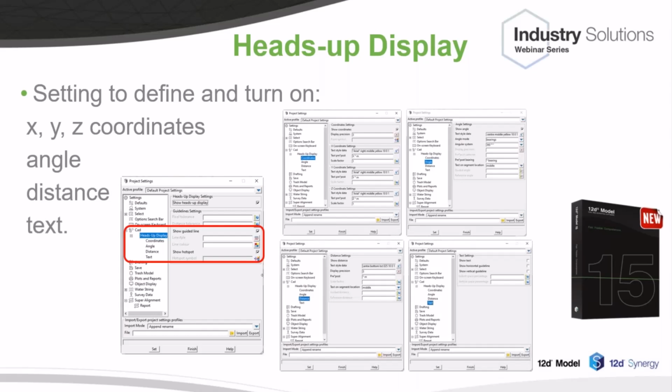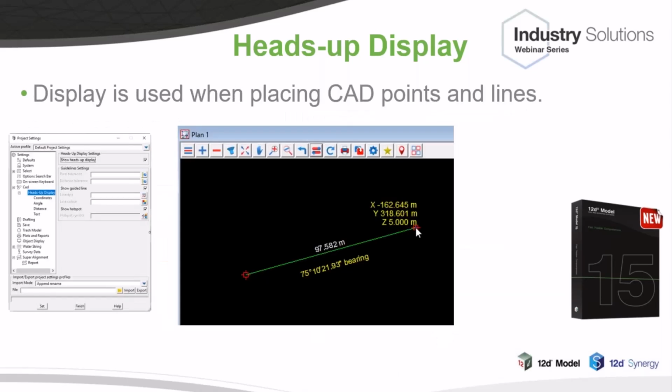So once you've set that, when you're using CAD for putting down a point or a CAD line, you'll start seeing this information automatically on the screen. It disappears, it goes to the next line, and then once you stop, it goes away. I've just set these up so it places them at different angles by different offsets. For these sorts of numbers, there's an offset from the segment, so it's easy to place them. It's not that hard once you set it up. I tend to use pixel units, so they're the same size on the screen, because you're looking at them on the screen.